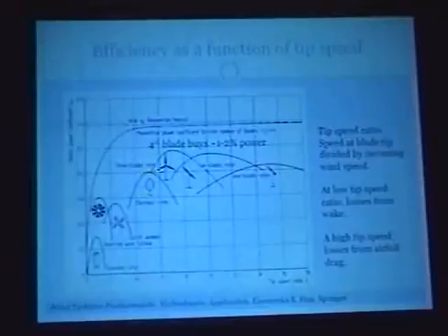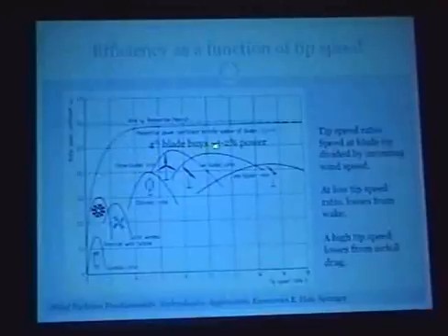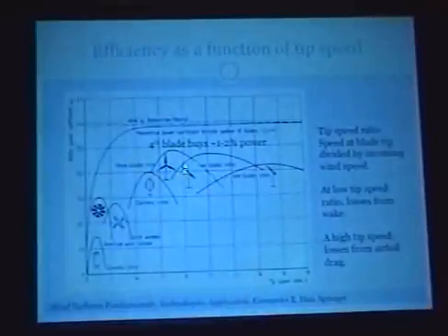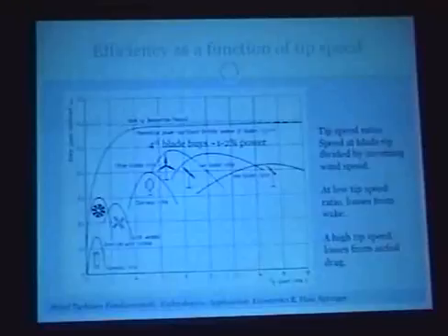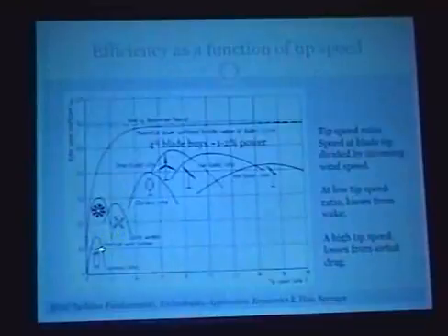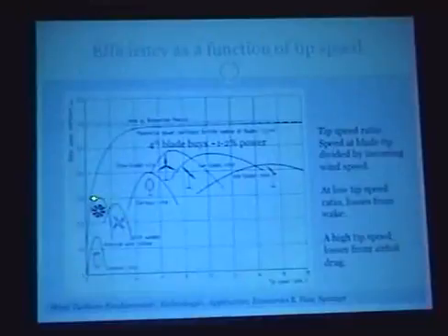And from the point of view of minimizing your cost, you see that if you have 3 blades and you add a 4th, you have to pay for a whole 4th blade, but you're not gaining a lot in power. So this is really a convenient sort of physical optimum and an economic minimum. And you can see that these older designs, like the wind vanes on farms, the Dutch windmill, and these sort of drum-type drag mills, are significantly lower efficiency, and they have much lower tip speed ratios.